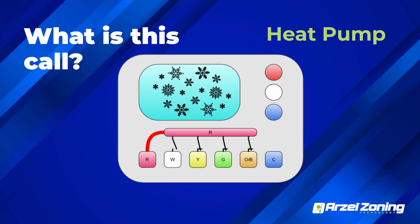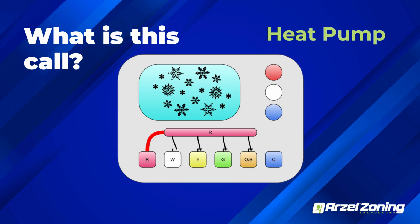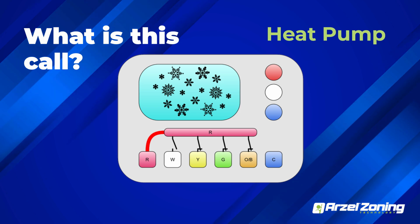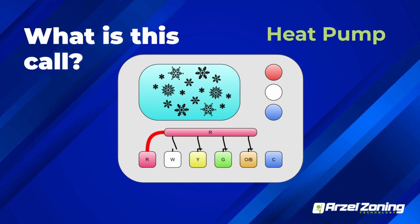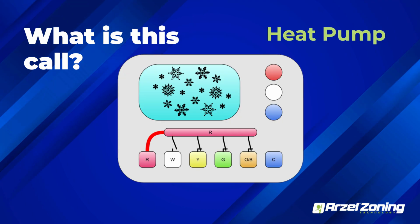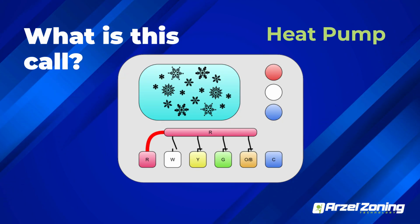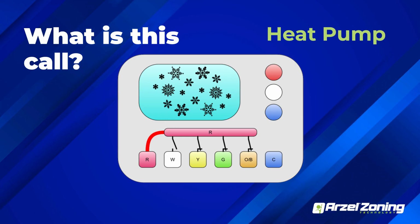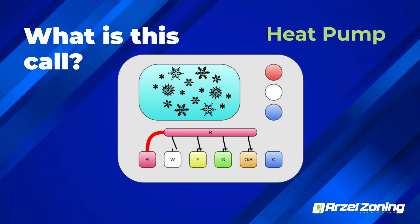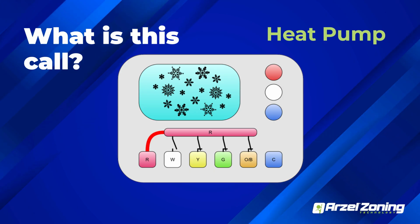Now, even if you have a piece of equipment where the reversing valve is energized in heating, like a Rheem Ruud or something like that, even though that specific piece of equipment requires a reversing valve energized in heating, from the thermostat, the Arzel panel always has the reversing valve energized on a call for cooling. And then through the panel itself, we control your reversing valve function to your equipment.